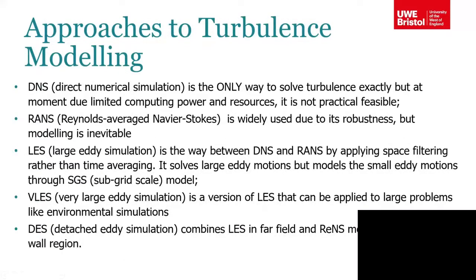The different approaches to turbulence are DNS, direct numerical simulation, the most expensive. Reynolds-averaged Navier-Stokes next, and LES, large eddy simulation. Then VLES, for large external flows. DES is the detached eddy simulation, a combination of LES and Reynolds-averaged Navier-Stokes modeling for the near wall region.